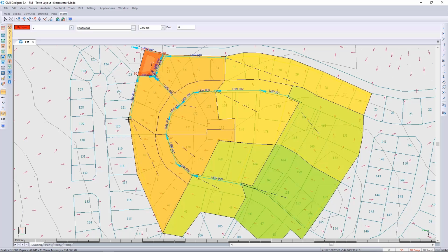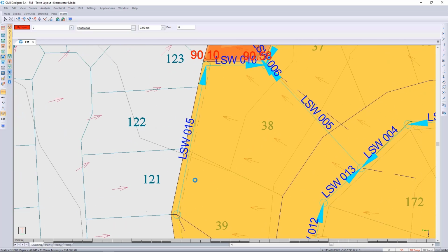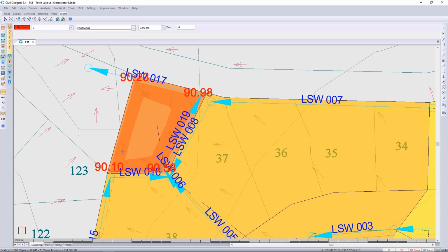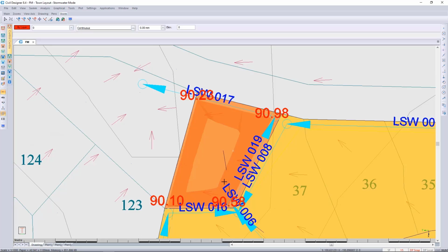You'll also see that I've got pipes running in this dip in the road here, or dip in the valley rather, and that dip in the valley I'm representing as a link, but not necessarily going to use that to put in as a channel. I just wanted to collect the water that was taking place and would probably discharge into the pond, controlled discharge over here, and I'd probably have a controlled discharge over here as well. The reason that I chose to outlet the water on the high side is I would like to have a controlled overflow on the high side of the pond and not discharge it on the low side, for erosion protection.